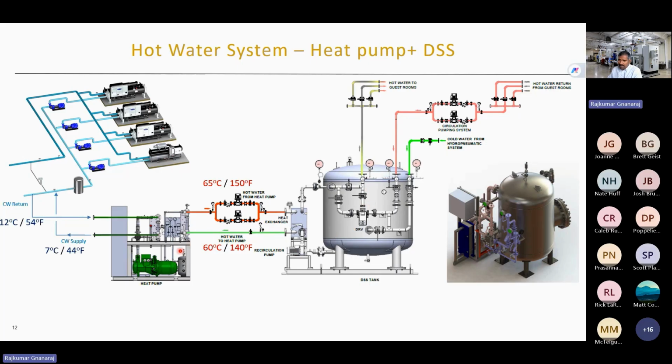For any heat pump, we need a tank for two different reasons. We'll see down the slides why we need a tank. But all the time, we are keeping this tank at 145 degrees Fahrenheit. And we supply the cold water when needed, and we supply hot water from the heat pump system. So when we keep it at 145 degrees Fahrenheit and above, the Legionella bacteria gets killed within a few minutes.